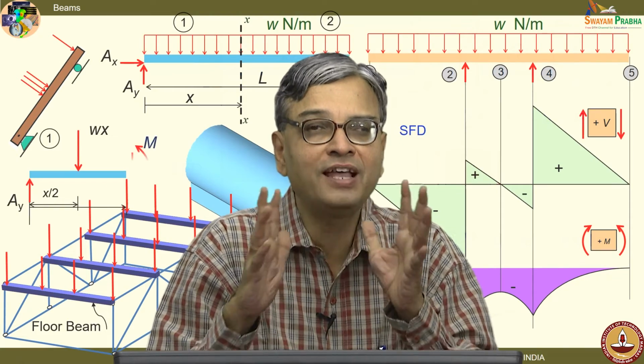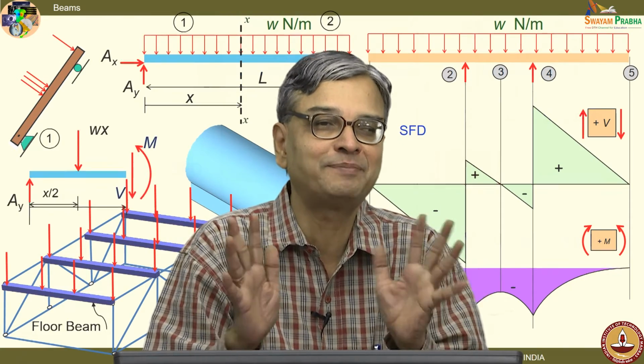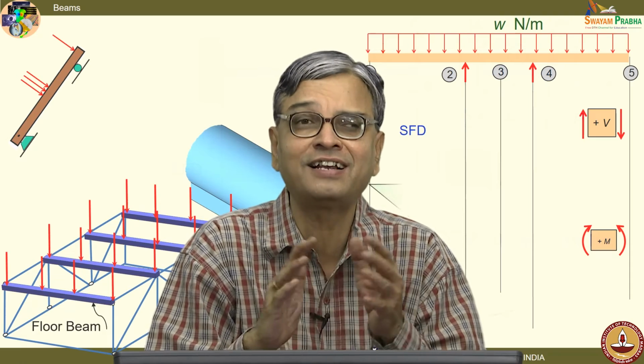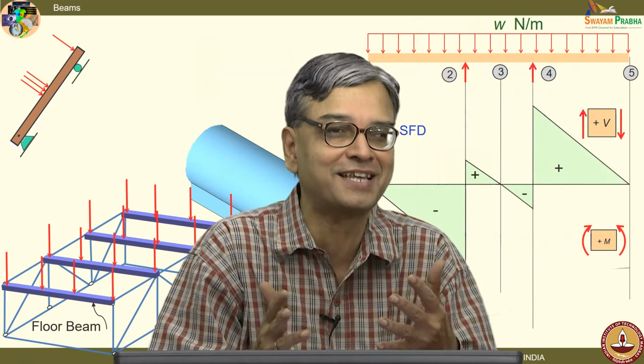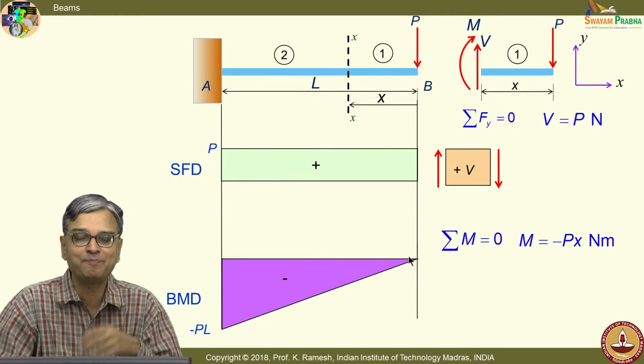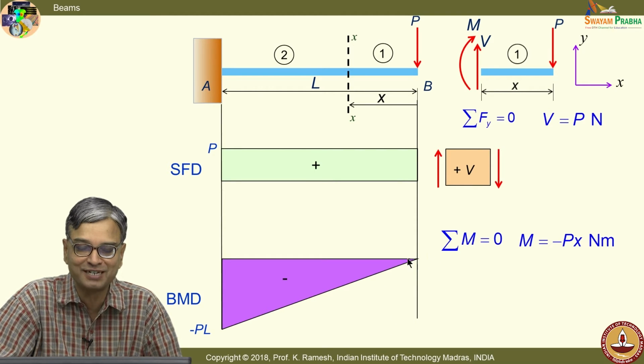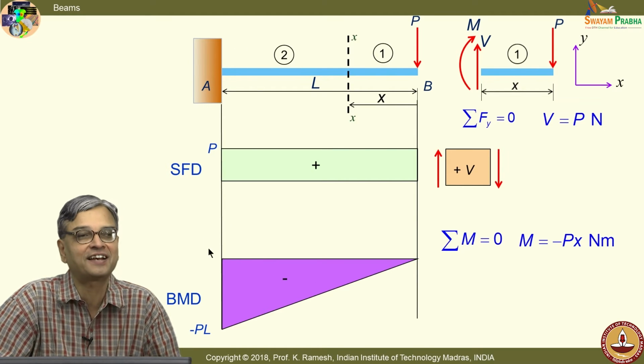They will always confuse between deflection and bending moment. It has always remained a puzzle. If they learn it correctly, there is no way they can make a mistake. Invariably, students will say in an interview, maximum bending moment occurs here, where the bending moment is 0 from your bending moment diagram, and maximum bending moment occurs at the fixed end.